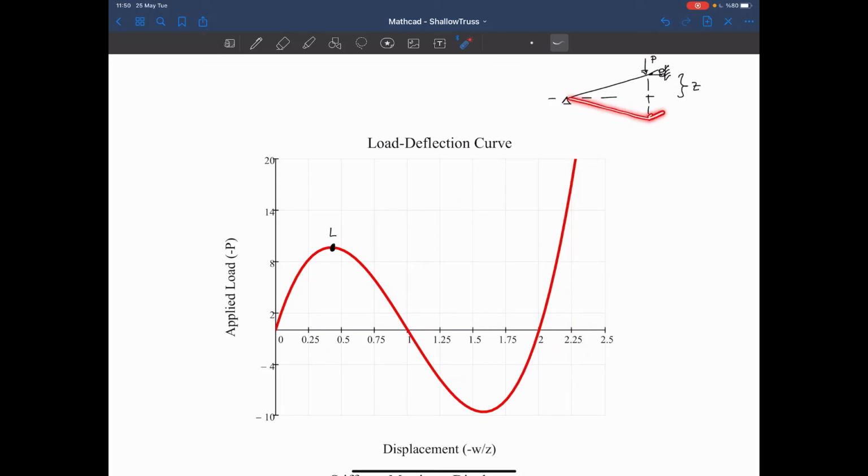we go to the reverse direction, now the normal force becomes a tensile force, and because of this reason we see another limit point somewhere here, and the structure becomes stable and starts to carry the applied loading in tension. So as this angle increases, we see more resistance in the vertical direction as also shown here. That's the load deflection curve, and from the simple example, we see a snap-through behavior